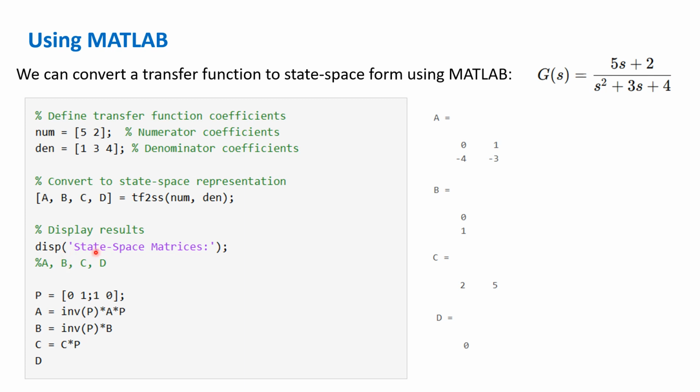Now, one thing to note is that state space representations are not unique. There are different ways to do it, and the MATLAB Control Systems Toolbox uses one method that's different from what our textbook uses. In order to convert the form that you get out from MATLAB into the form that our book uses, we're going to use the following conversions. We simply multiply by an identity matrix, and when you do that, you get out exactly what A, B, C, and D are, exactly like our textbook gives us.